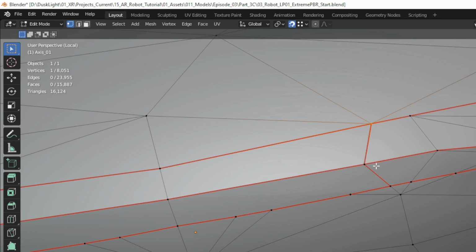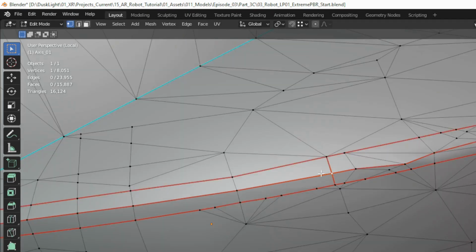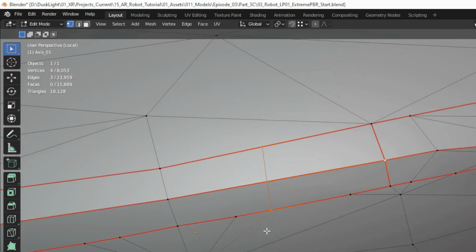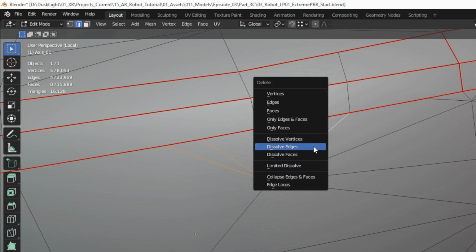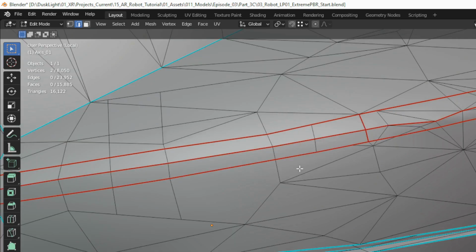And if I want to move this vertex here, I'm just going to deselect the magnet, clicking on the vertex, pressing the G key twice, and I can move this edge along. So I clean this up. I think I want to introduce a little bit of topology, otherwise I get a huge quad. So that's one. I don't like that this huge pole is present underneath the part we just cleaned up. So I'm just going to delete all the diagonals. I'm going to dissolve those.